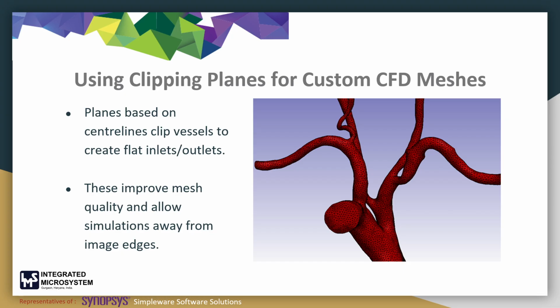So for computational fluid dynamics meshes, we use clipping planes for custom planes based on the centerline to clip vessels and create flat inlets and outlets. These improve mesh quality and allow simulations away from image edges.